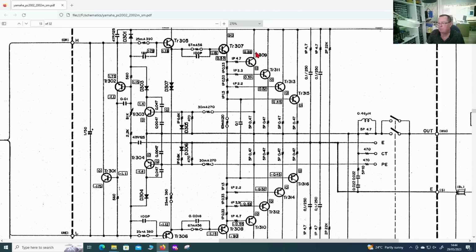So first of all, just this transistor is driving the speaker. 0.2 volts higher, this one comes on. So we now have 2 transistors driving the speaker, and you can see just after that, 0.52, this one comes on, and then sometime later, quite a while later, another 0.7 volts on the drive, this one comes on.